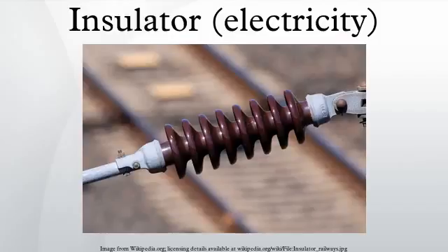This occurs because the valence band containing the highest energy electrons is full, and a large energy gap separates this band from the next band above it. There is always some voltage that gives electrons enough energy to be excited into this band. Once this voltage is exceeded, the material ceases being an insulator, and charge begins to pass through it. However, it is usually accompanied by physical or chemical changes that permanently degrade the material's insulating properties.